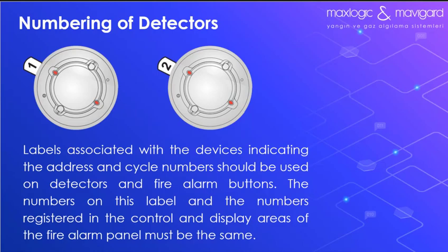6.5.5 Identification. The control and indicating equipment may have the ability to individually recognize the detector or alarm button that the alarm is given from. In this case, a method should be provided to ensure that the indicator of the control and indicating equipment is associated with the relevant detector. If detector tags are used to provide the necessary cross-relationship between detectors, alarm buttons and the control and indicating equipment panel, identification numbers or letters must be added.